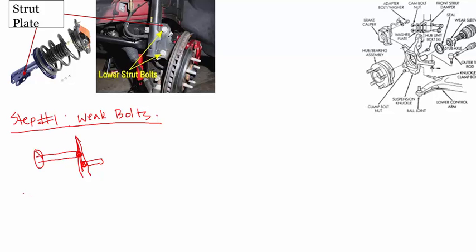To find that force, if we want to calculate the allowable load or stress for which this bolt will be okay, the allowable load on this bolt is the allowable stress times the area.